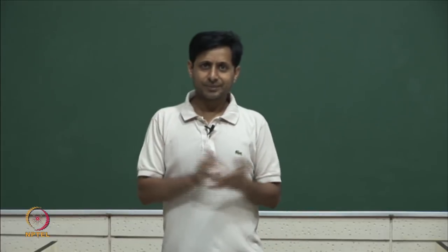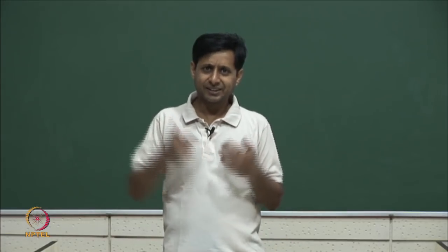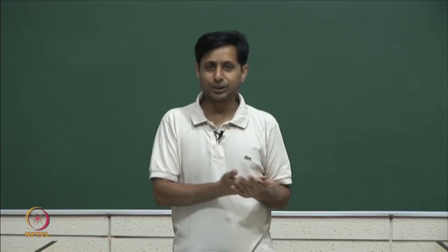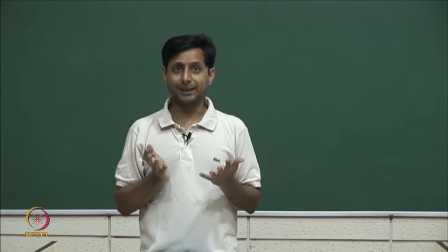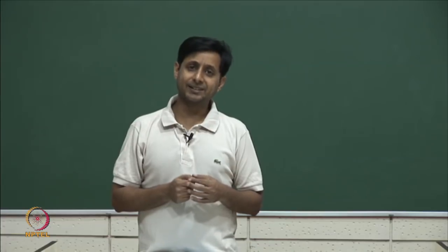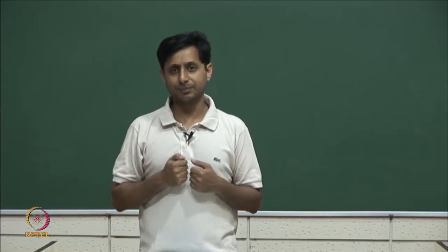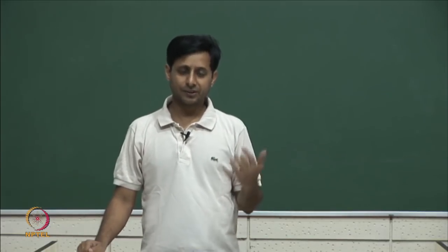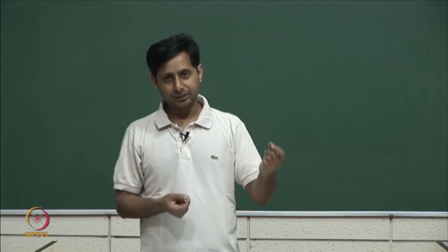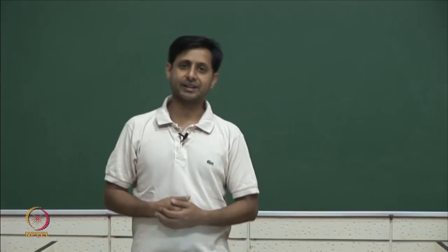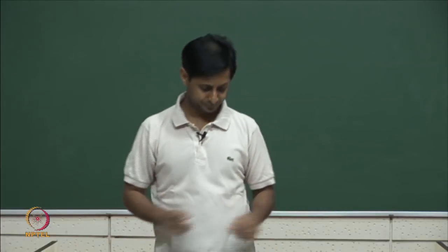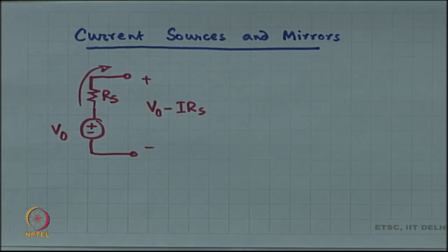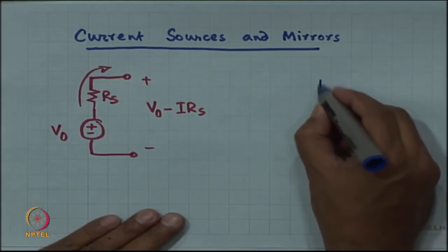But anyway, by the way, we had discussed this earlier, it is all relative, it is all subjective, whether a voltage source is at all a voltage source or a current source is a subjective matter. Why? Because it all depends on the quality of the output impedance. Okay. In general, it is a power source, it is a source of power, whether it appears like a constant voltage or appears like a constant current, it is for you to decide. Okay. So, this is the model for a non-ideal voltage source, and a current source